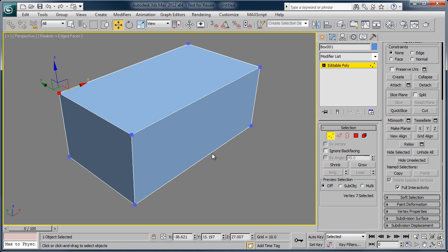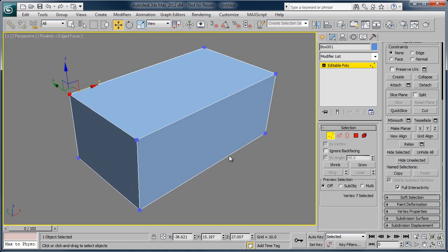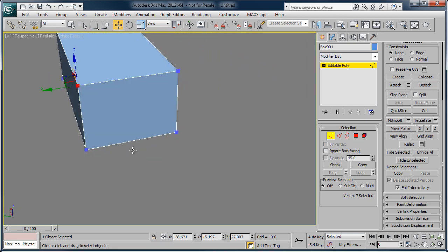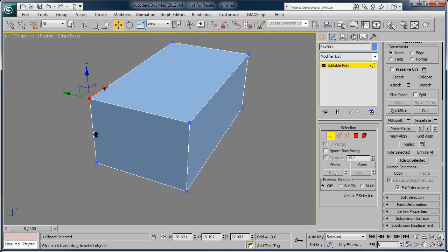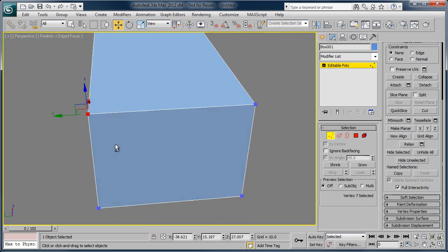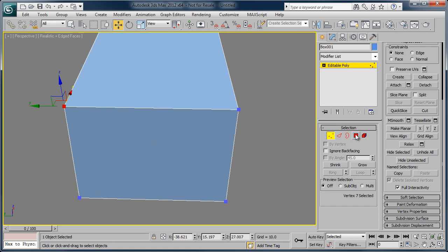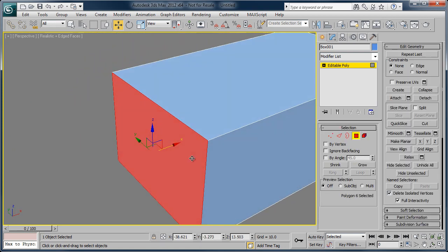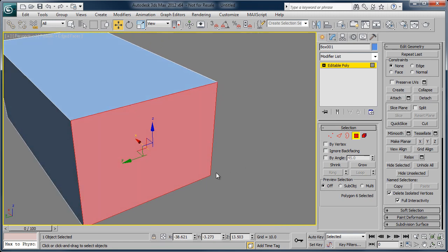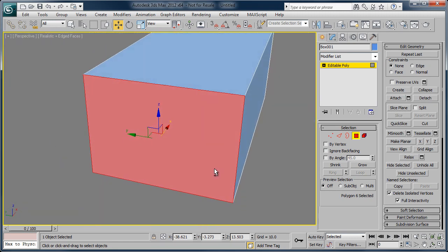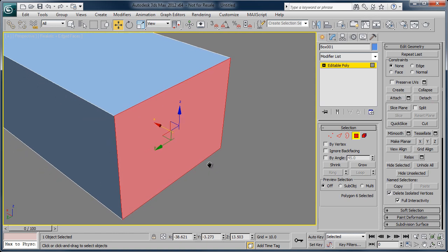And so when we begin, if we look at Vertex Mode, there's a couple things you'll notice. Once we've selected our vertex, if we hold down Alt and the middle mouse button, the camera starts to rotate around that sub-object that we have selected. For example, if we click on Polygon, you'll notice that the camera is orbiting specifically around that area. But there is a setting you can change to ensure that the camera operates the best way for your usage.